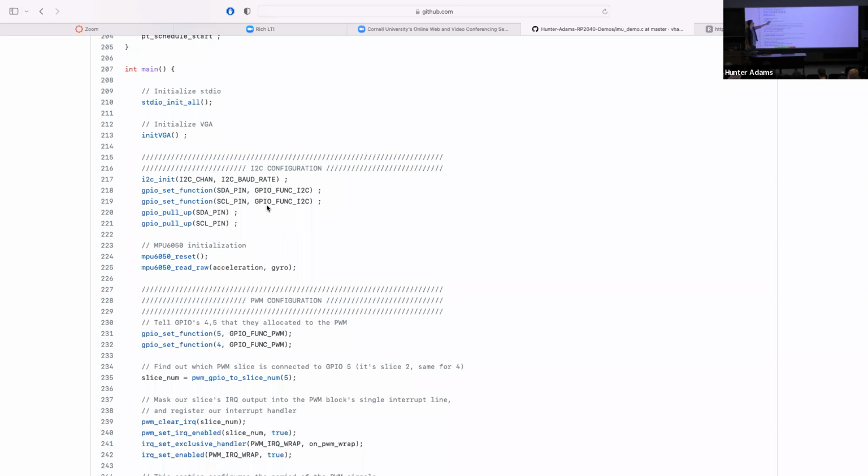So my expectation of what might be going on there is this MPU 6050 reset, there are I2C transactions that occur there. And if one of those fails, it blocks, right? So it just freezes the whole program. And probably what's happening is if you reset the Pico, the IMU remains powered, so it remains in this hung state. And so what you discovered is you have to actually remove power from the IMU and then power it again to get it out of that hung state, and then things worked more reliably? Yeah. Okay, okay. That's really good to know. Any other questions or bugs from any folks?